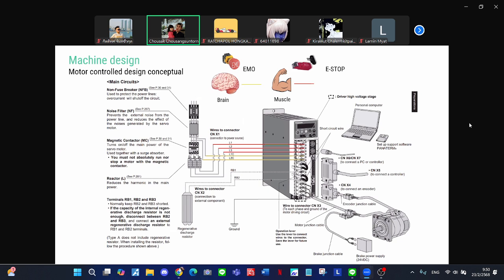So in this case, a recovery process will be needed, which typically involves homing the actuators or recovering the last position, bringing the machine back to its starting position. The process may take up to 20 minutes,